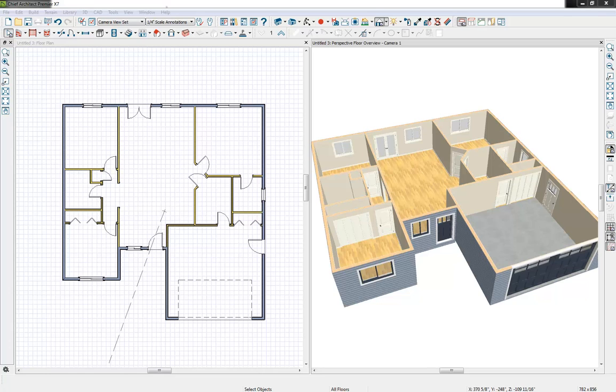Now when we're dealing with a remodel, we're oftentimes dealing with various wall types that you'll want to display in your plan. And typically what you're looking at is you'll have existing walls, perhaps you'll have some demo walls, and then you'll also have new walls that you're creating in the plan, perhaps within the structure, or maybe you're doing an addition. In this particular project we'll be doing all of those. So we'll want to add some wall types, and if it's not already done in your particular program, we can add wall types and they get saved to our list.